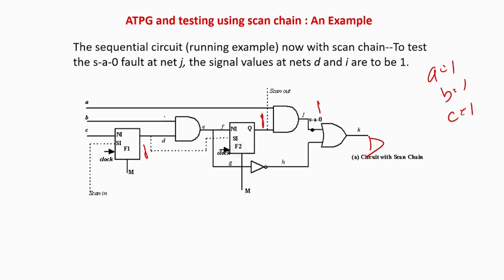So now if B equal to 1, this is 1, D is already equal to 1, apply a clock pulse, the output will be 1. So 2 patterns will be extra required to settle the business of the 2 flip flops in the chain. If there are more flip flops in the chain, this problem will actually blow up, and you have to find extra algorithms. In fact, people have already tried it.